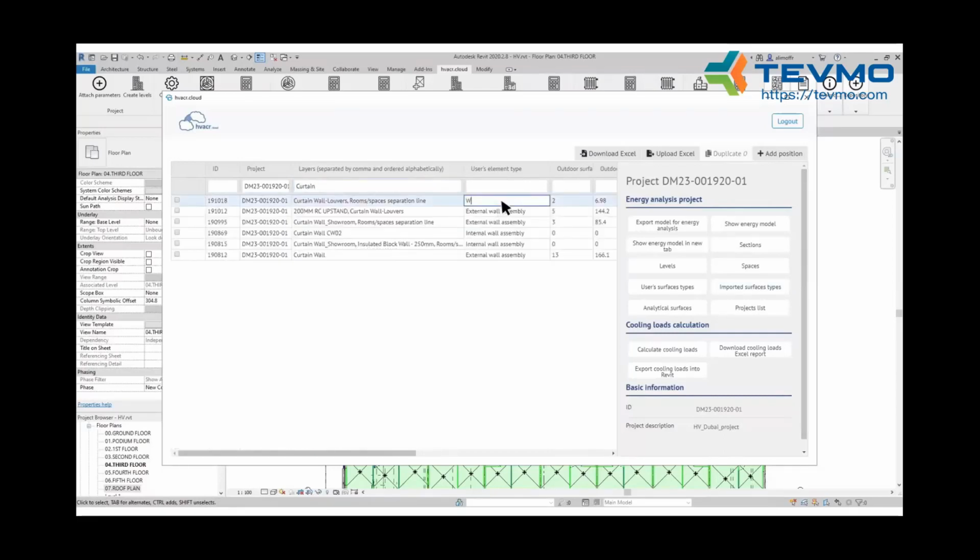And this is one more method. It wasn't shown in previous videos, but it's very important. In previous videos, I showed you how to change some surfaces on the 3D model. So you choose the surfaces on the 3D model and assign them a new surface type. But there is one more possibility. The table that is open now is the table of all surface types inputted from Revit.